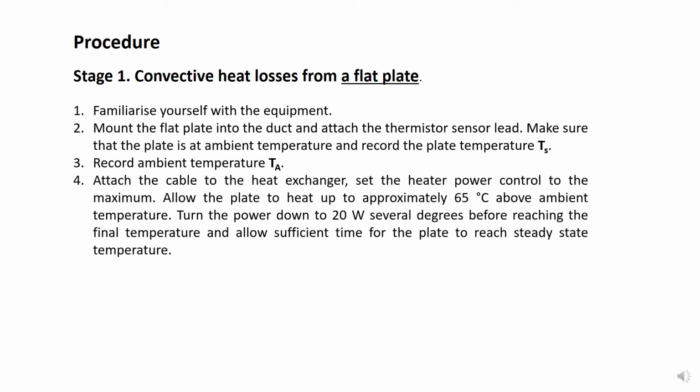Well, next, we need to attach the cable to the heat exchanger and set the heat power to the maximum and allow the plate to heat up to around 65 degrees above ambient temperature. Then, we need to turn the power down to 20 volts when the temperature is nearly reaching the final temperature, and we need to wait sufficient time for the plate to reach its steady state temperature.